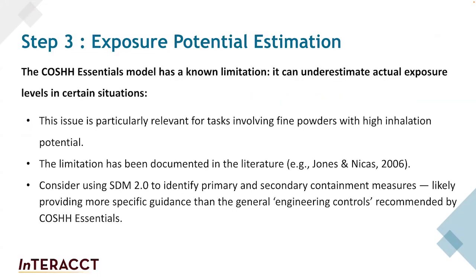The COSHH Essentials model is a useful tool, but it does have a known limitation. In certain cases, it can underestimate actual exposure levels. This limitation is particularly important to keep in mind for tasks involving fine powders with high inhalation potential.